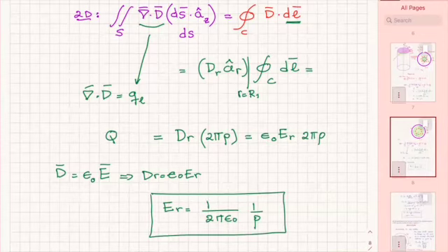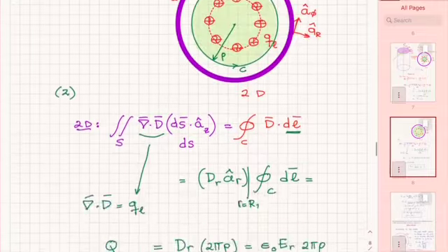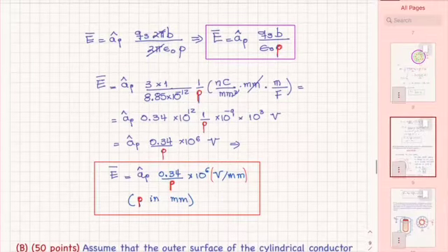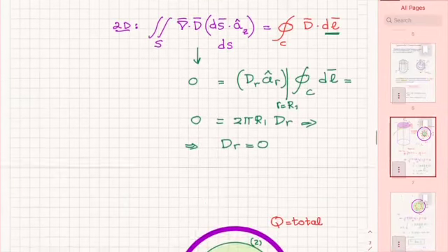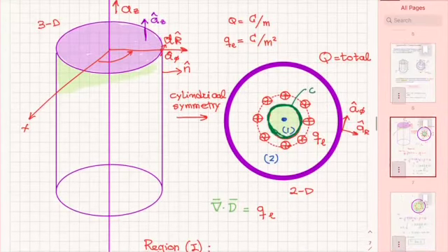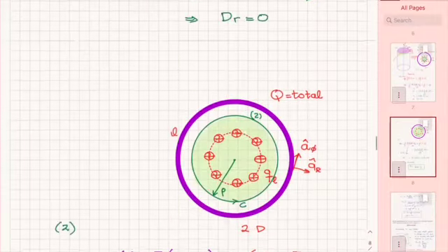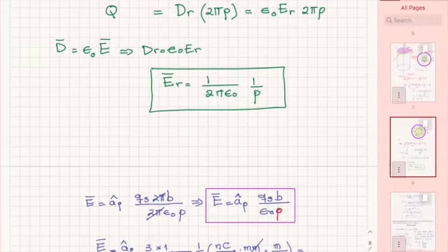And that's going to be your E bar, which in fact is what we found here. And it's going to be along what direction? E bar along the direction of D bar. And D, you remember what direction D has? D has the rho or R direction. So this is going to be along the a sub r direction. So it's going to look outwards.